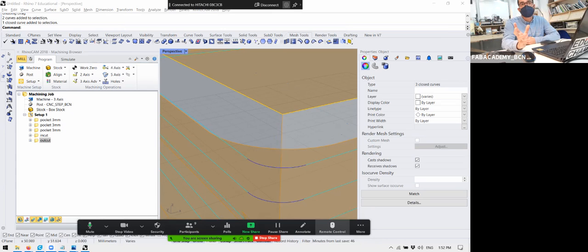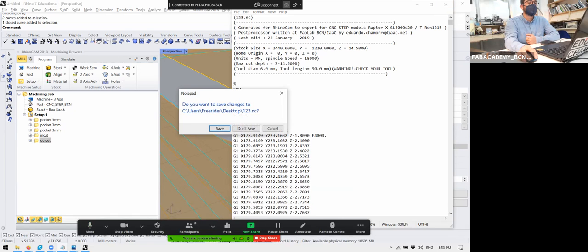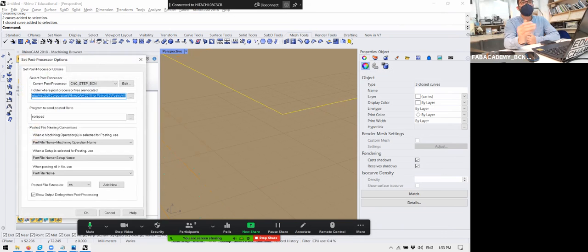Yes, there are a lot of types of G codes and how you interpret. And for example, some machines, for example, this machine, M5 and M8 is the same command, but this machine doesn't read M5, only reads M8. So the post processor does final tweakings for your custom firmware of the machine, if you want to. You need the post processor for the machine you're using. You have the chance that your machine can read multiple types of post processors. Yes, but that's, for example,